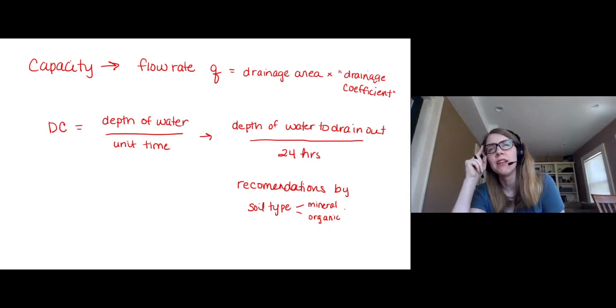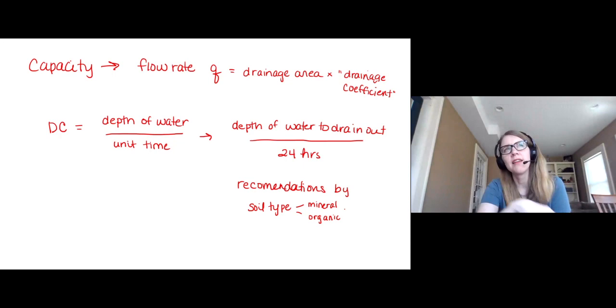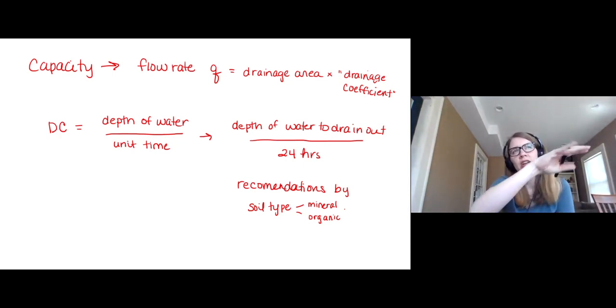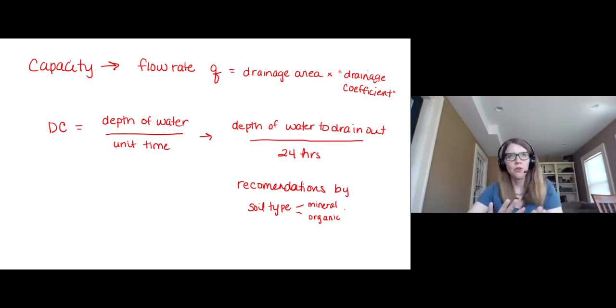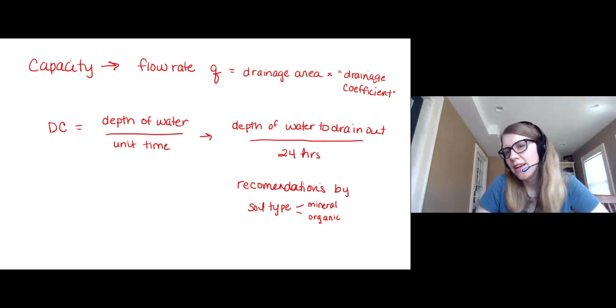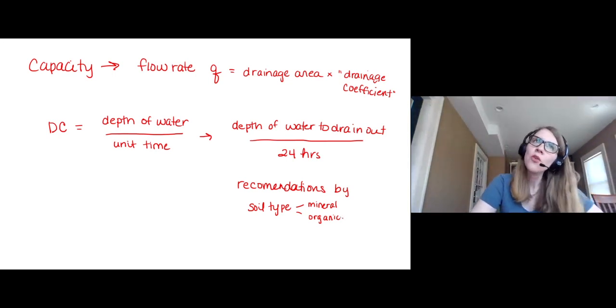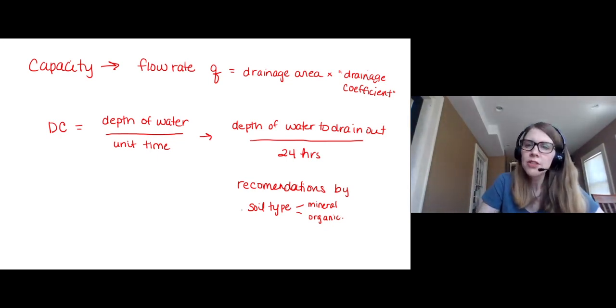You remember when we were talking about soil-water relationships, and we were showing the relationship between soil water content and soil suction pressure, and the sand, silt, clay soils had sort of a range of graphs, and then there was the peat soil doing something all by itself. That line was way out there. That would be an organic soil. The other soils are primarily mineral particle sizes, doing more of a clustered thing, so we lump them all together for the purpose of drainage coefficient.